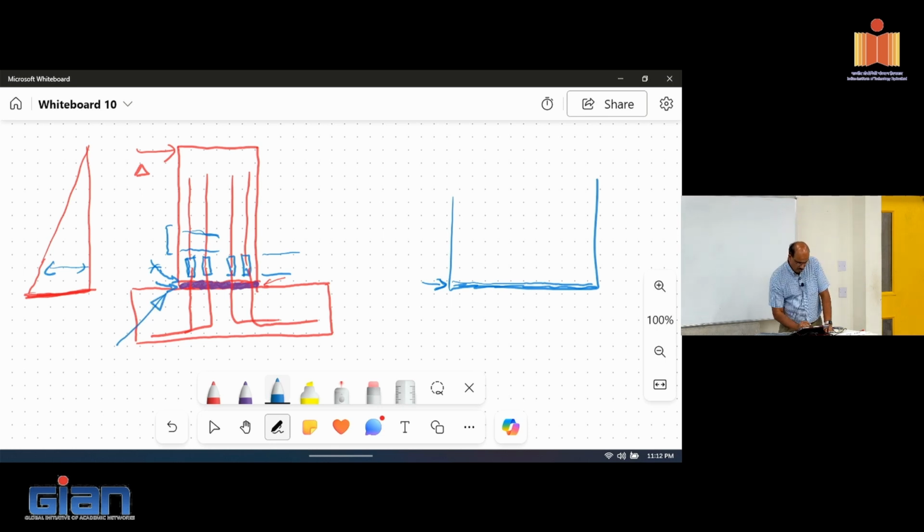One is that all of this deformation has to happen somewhere, so it tends to happen here. We also talked about strain penetration. In both cases, these bars will have the penetration effects, and therefore this crack will be a lot wider, which you can see in all of your tests as well. The crack gets wide open.